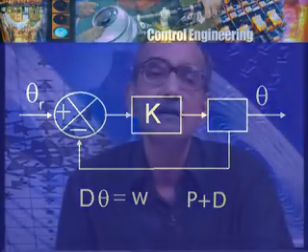For what reason? The main reason for introducing integral feedback was to reduce the error due to load torque variation, that is, the effect of the disturbance variable. That is where we introduce the integral feedback. In this case, one can see that it is not necessary to introduce the integral feedback to take care of the load torque disturbance, because ultimately the motor is to come to a steady position, theta r very close to theta.